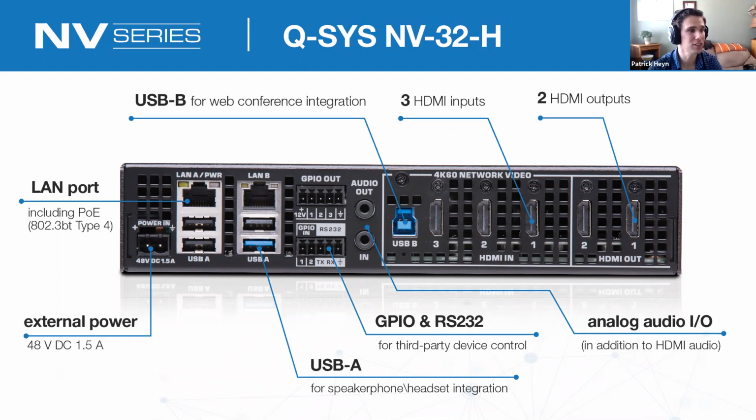I see a couple other questions. I'm going to unmute Kurt. I think these are pretty easy, but I'm going to open them up anyway. He's asked, do you need AVB if you plug directly into the core with a USB? And the answer is no. That is the other optional bridging device that you can use. If you're using a Core 110, you can use the USB port on the back to do bridging directly from the core, which means you don't need a USB bridge if you're just running a short run from a rack-mounted core to a rack-mounted PC. You just run that directly from it.